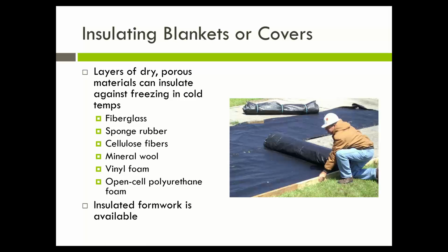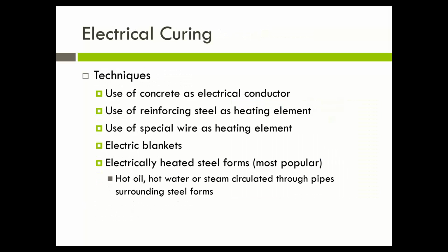In the winter, we may not need to supply additional heat if we can capture the heat that's occurring due to hydration. And if you recall, we measured some of those heats of hydration. You can use insulating blankets, you can use insulating formwork, you can do all sorts of things to trap the heat in and passively heat the concrete by using that heat of hydration.